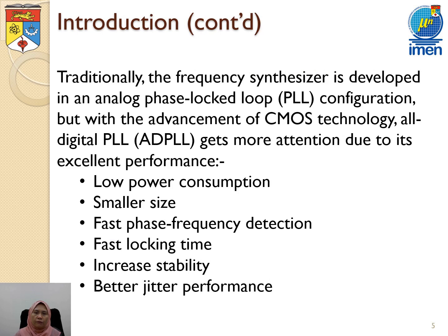Traditionally, the frequency synthesizer is developed in analog based loop, or PLL, configurations, but with the advancement of CMOS technology, all digital PLL, or ADPLL, gets more attention due to its excellent performance in terms of low power consumption, small size, fast frequency detection, fast locking time, increased stability, and better jitter performance.